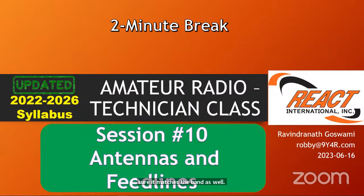Thanks. Good question, Norman. Edward asks, the various meters are useful for measuring zero. Do these instruments need to be connected always, or is it just a momentary snapshot used to tune and then it can be disconnected? That's an excellent question. Many hams leave them in line right through, especially for HF. On VHF, hams tend to put it in, check it, and then remove it for VHF, UHF, those bands, right? I don't know too many hams that leave an SWR meter in for VHF and UHF. Some may not. You just want to check it and see that it's okay.